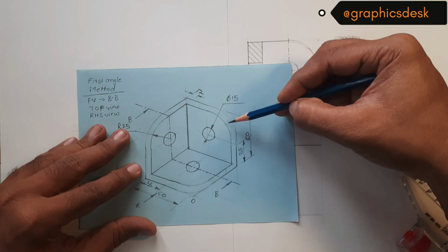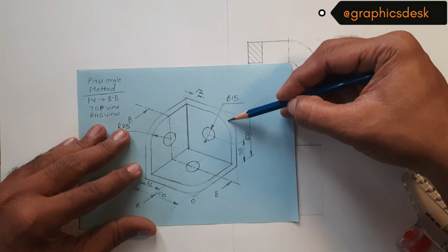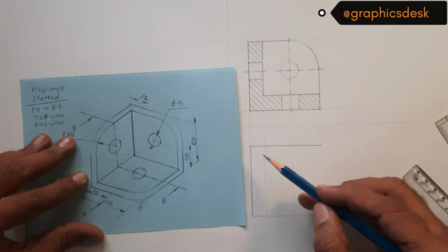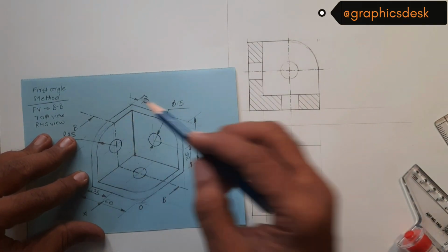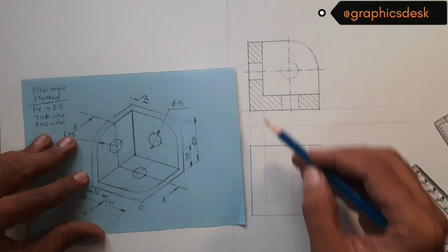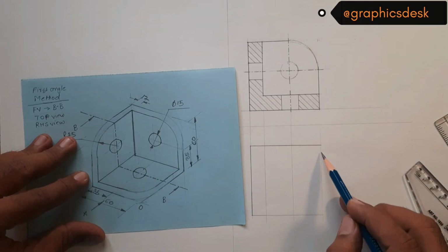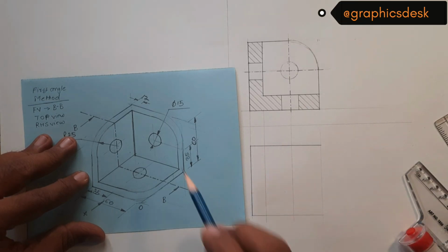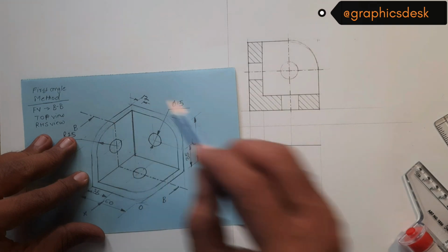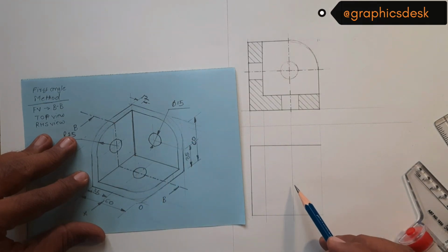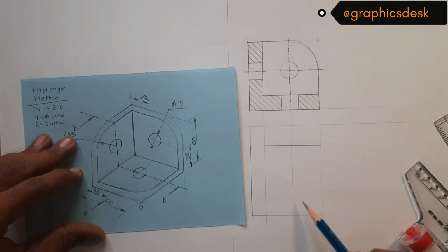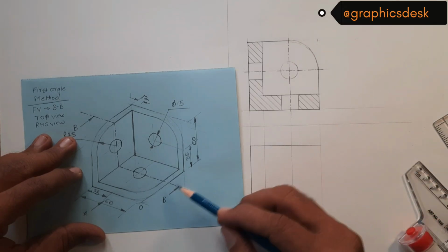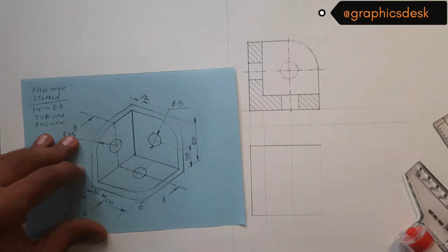This particular part of the geometry which is visible will be here with the width of 12 mm, which is already given, and this is this particular face. So this is already marked or available from the projection. You have to mark 12 mm in this direction, which will give us this shape representing this particular face, and then a hole at this point, which is 25 mm from here, or you can measure 35 mm from the top face. That means from this face, this particular center is 35 mm. So let's mark that.